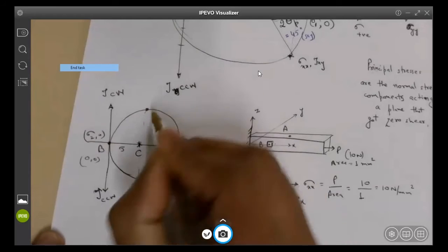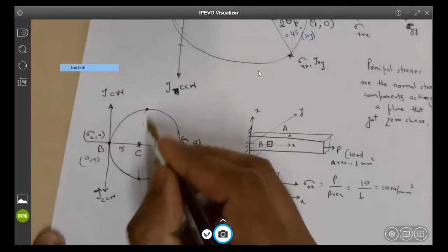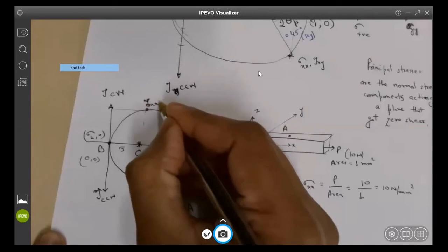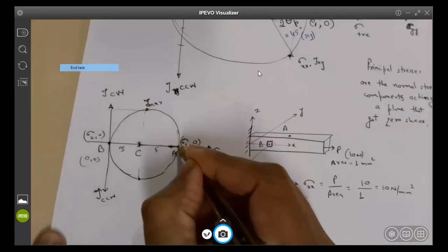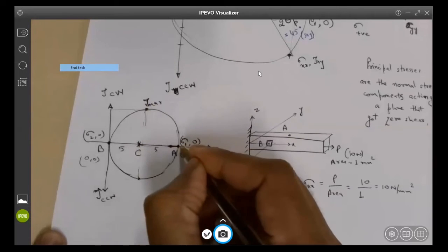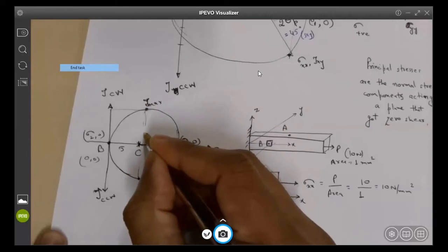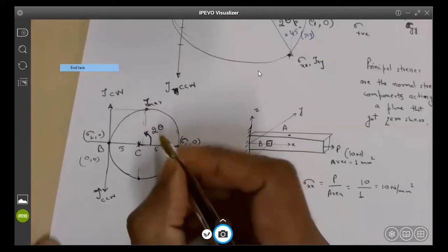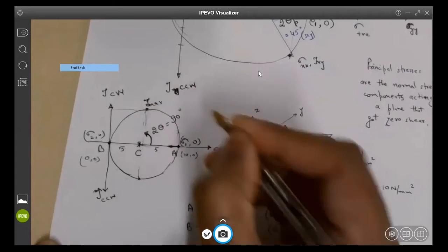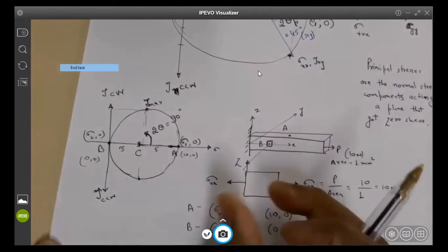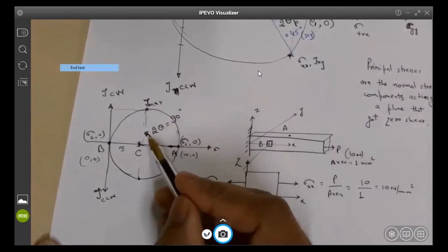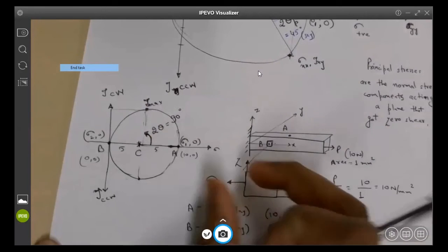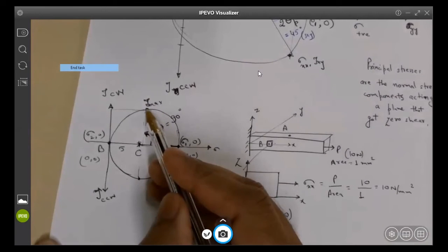So we basically look at first the positive part. Both of them have got the same maximum shear stress. This is the maximum shear stress. And at what angle is that maximum shear stress happening? If you see, this is the principal plane on which the stress is acting, and this angle is 90 degrees. And if I rotate my stress element by half of this, because this angle is 2 theta, I will reach a point where I will get a maximum shear stress component, right?